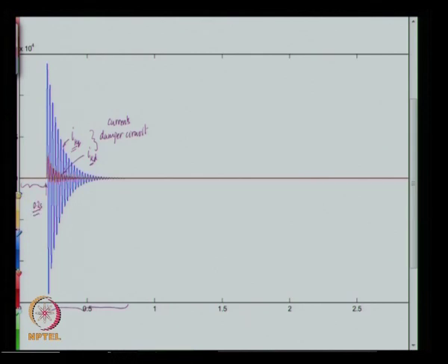That is why you see that no current flows until this time, and then there is some large current flow in ikd and ikq, but they decay down to 0 pretty fast, and after that there is no damper current, which means that in this interval one can neglect the existence of the damper bars.